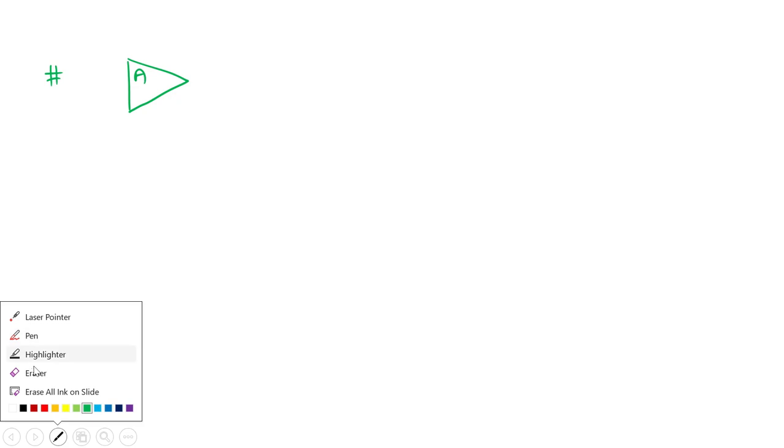So if I am using this gain block by using some sort of GM cell, we can analyze it in this way. This is our amplifier block, and it can be implemented by using the GM cell, and its current is fed to some load, which here is nothing but the parasitic capacitance, since no external load is applied.